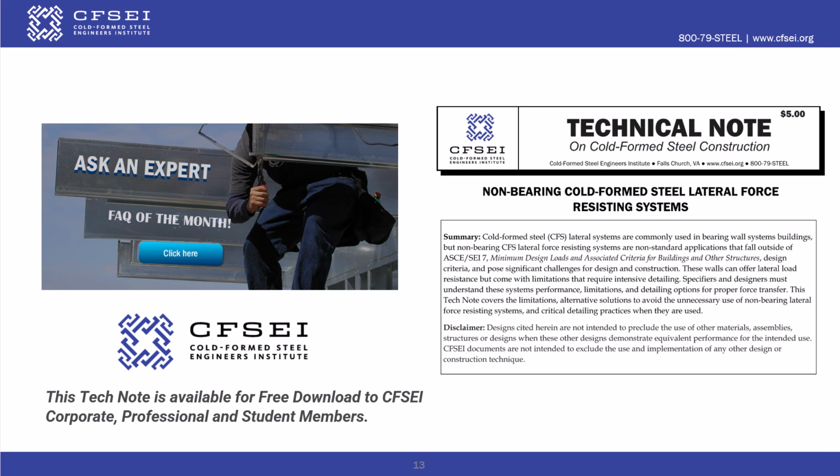Summary: non-bearing cold form steel lateral systems are not recommended for new construction. When used, they require intensive detailing, careful coordination, and clear documentation. Alternative systems that align with the building's gravity system are typically more practical and cost-effective. For full technical guidance, refer to the complete tech note L400-25 available from CFSCI. This video provides a high-level overview, but the note itself contains detailed engineering insights necessary for proper application.